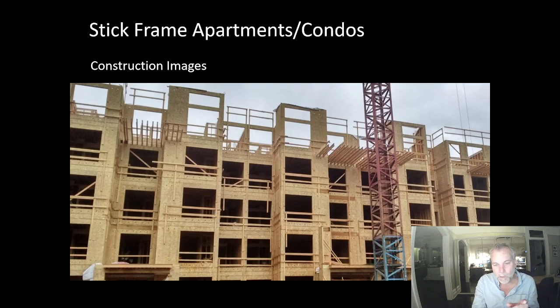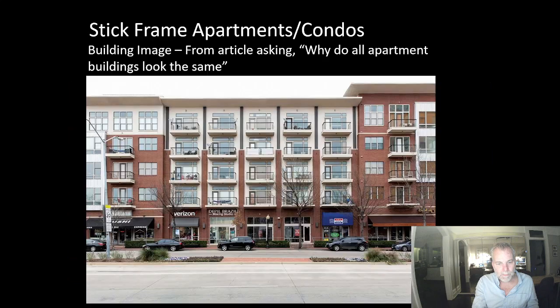And punched openings can be a problem. So we have to design very, very carefully to make sure that there are not too many windows and the windows aren't too big to affect the wall's ability to resist lateral loads. I want to point out, you have probably seen examples where this is not the case, but you can see